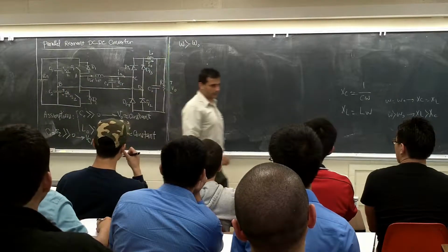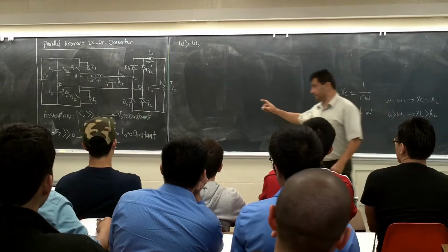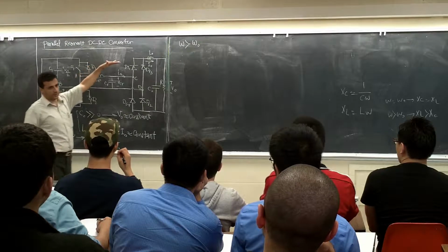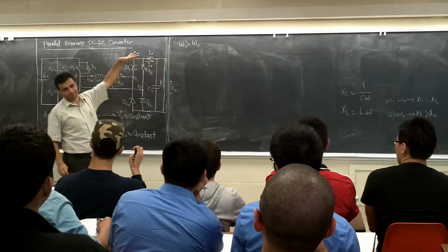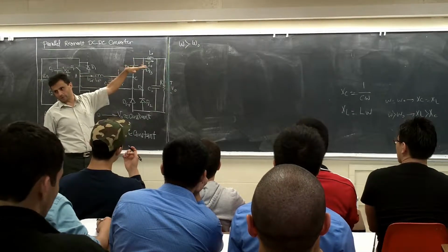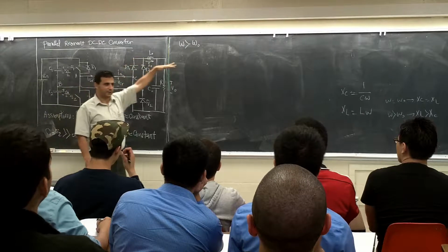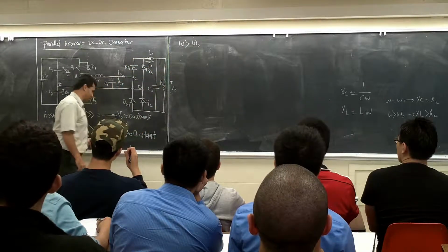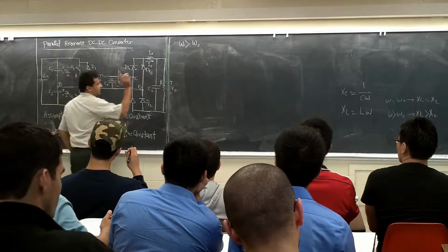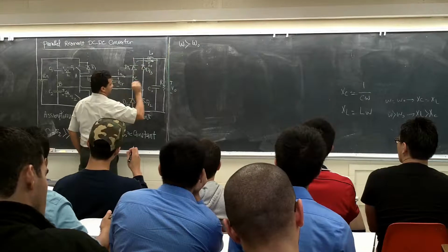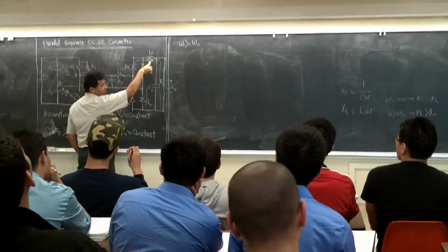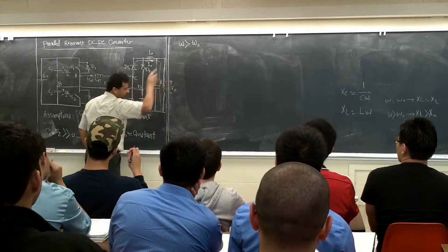So that's from this side. Now, let's look at this side. This is new. First of all, this current is a DC current. Remember, in the power electronics course, we call it a highly inductive load, right? As soon as we mention it is a highly inductive load, it means the current is constant, right? Now we are saying the same thing. L is very big, so basically the current is constant, right? Now, this current can go through here, through D1 and D2, right? This current is not going to change its direction. It's always this way, right?